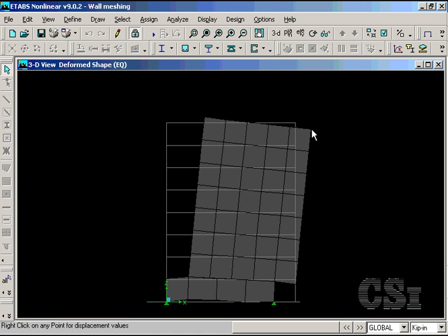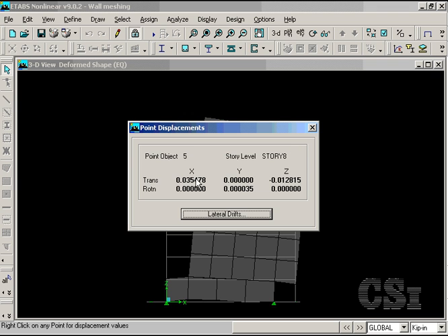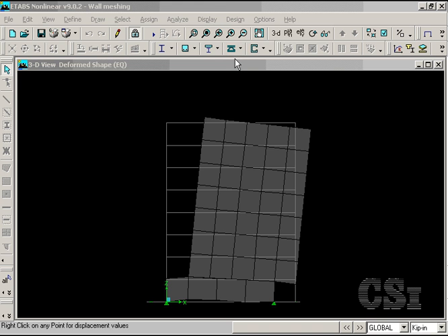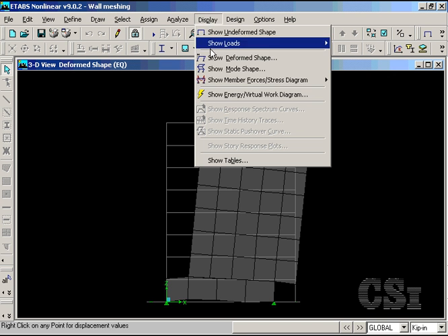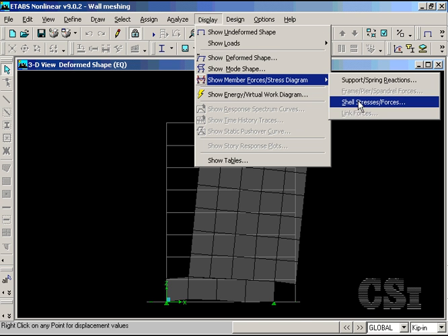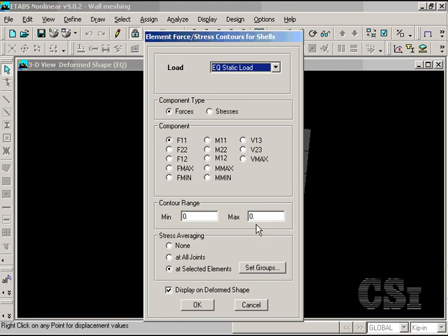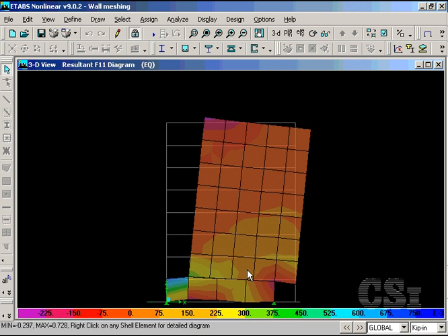Running the analysis this time gives a displacement approximately 10% stiffer than that for the refined mesh without line constraints, and a force plot that still seems reasonable. This model is an effective use of the line constraint option.